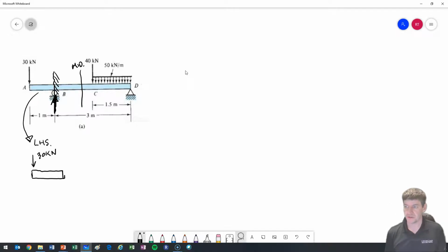And so if I'm just trying to find the moment, or one of my values for V, then I'm able to just solve it without finding all of my internal loads. I just won't put that internal load on my free body diagram. But I do need to have a V and an M. So I'm going to put down, just put it going up.